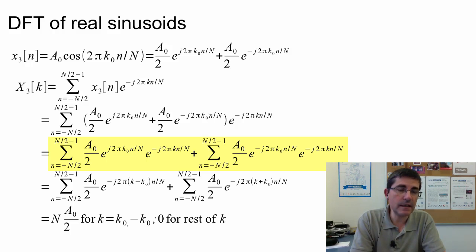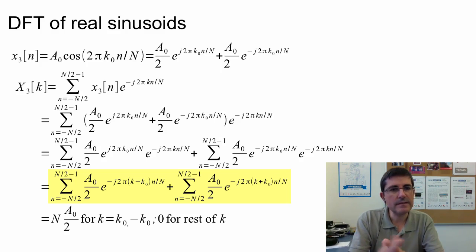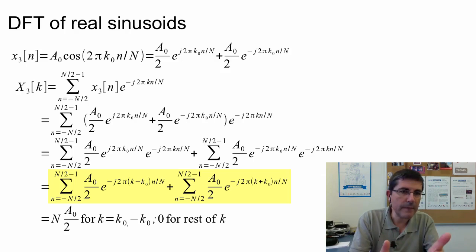The DFT being a linear function, and we will talk about that, we can express the DFT of this sum of two complex sinusoids as the sum of two DFTs, one for each sinusoid separately. Therefore, the result is two DFTs that we have already seen. One is of a negative frequency, and the other is the DFT of a positive frequency, each with a given amplitude.